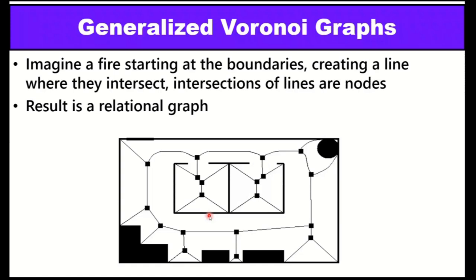It is creating nodes. It is actually a result of a relational graph. Now the whole scene is decomposed into a line diagram. The obstacles are grown dark, and now in the free space, nodes are generated, and now paths can join in a straight line or on ordinary lines. So it is exactly a line diagram.